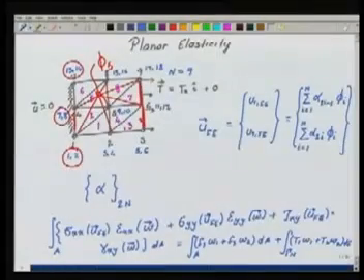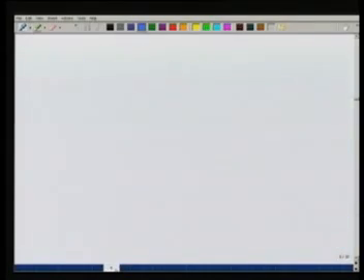So this will give me my element stiffness matrix. Similarly, the load vector entries that we can then handle, and do the assembly to get the global system. Then in the global system I go and explicitly impose these boundary conditions for alpha 1, alpha 2, alpha 7, alpha 8 and so on, and solve the system to get the solution.